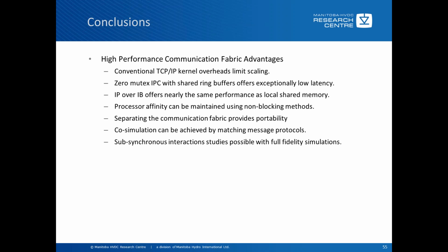Separating the communication fabric from EMTDC itself improves portability. We have also built a co-simulation interface using the fabric that just requires matching message protocols between each side. And so you can simulate between EMTDC and some other program, whatever that may be, even a mechanical model, for example, of a wind turbine. Also, subsynchronous interactions are now more possible to study because we have full fidelity.